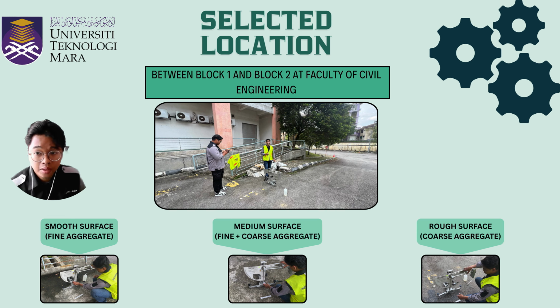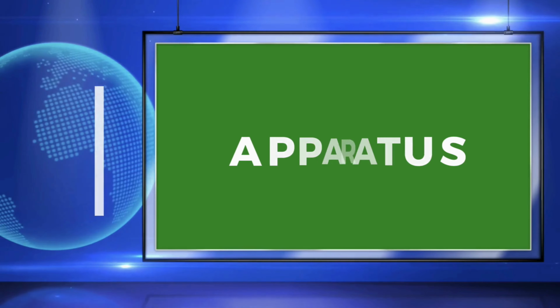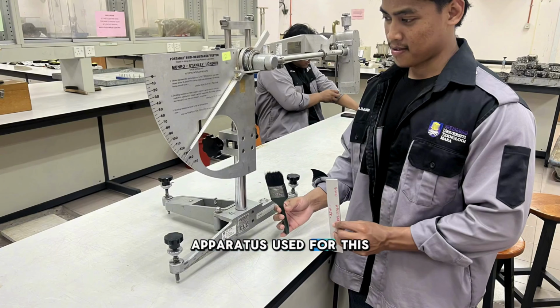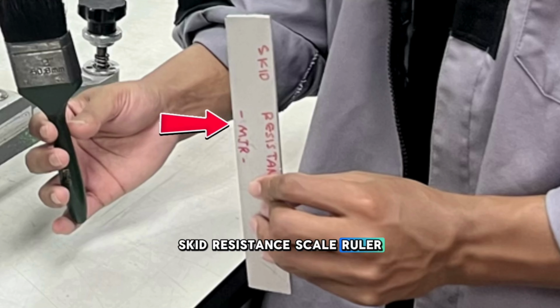Engineering. First, we test a smooth surface which has fine aggregate. Second, a medium surface which contains a mix of fine and coarse aggregate. And third, a rough surface which has coarse aggregate. Apparatus used for this test are the portable pendulum skid resistance tester, scale ruler and brush.